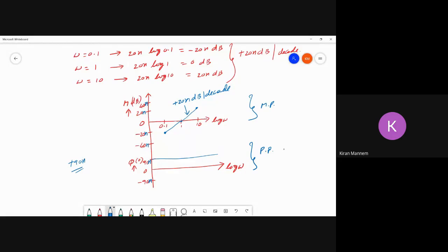So we replace 20 dB by 20n, and the phase angle and magnitude are multiplied by n. Similarly in the case of poles. So this is another basic factor, Bode plot.